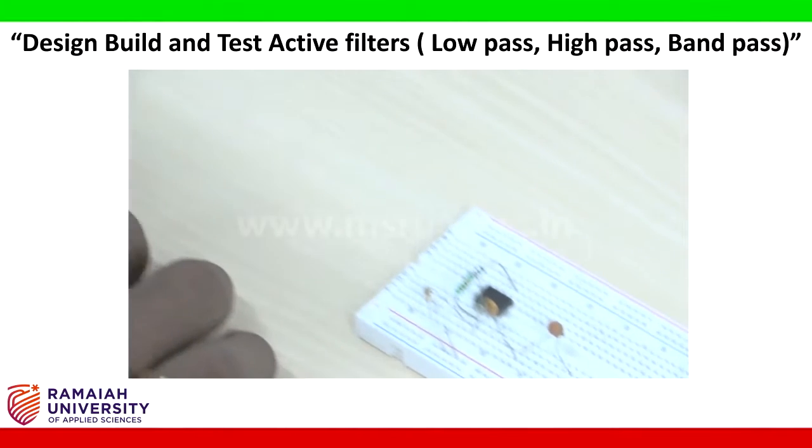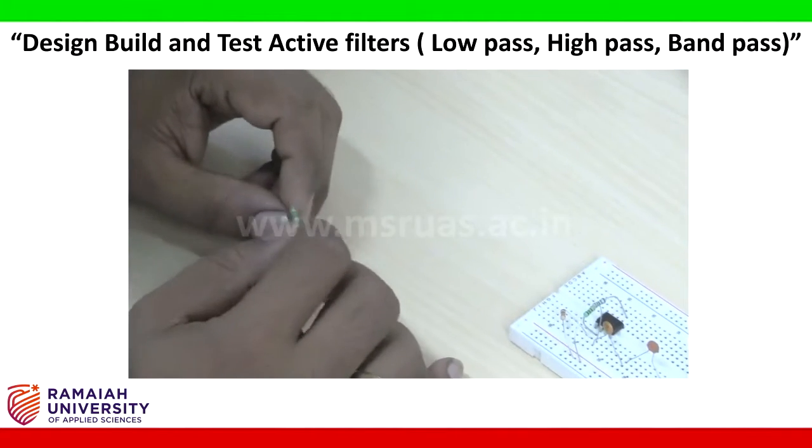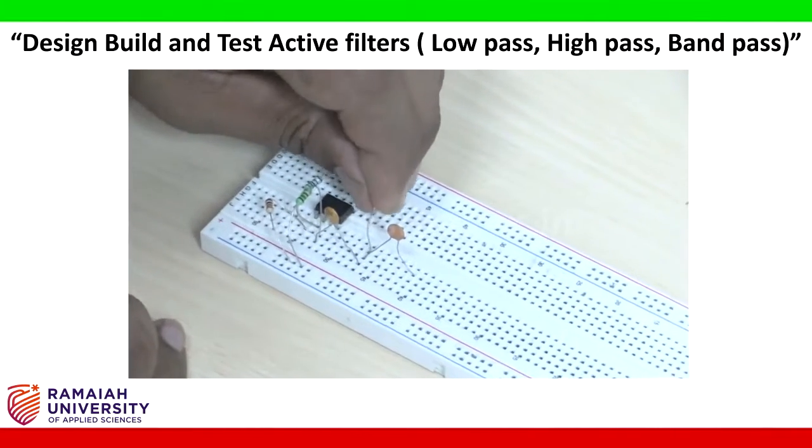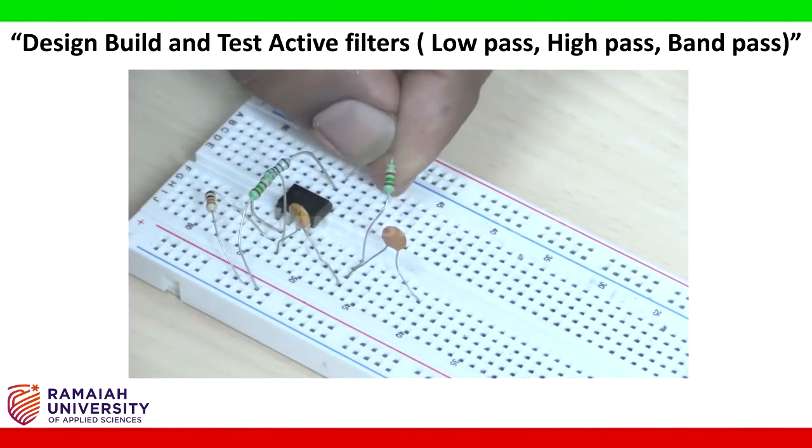After that I am taking a 1.6 kilo ohm resistor, and this 1.6 kilo ohm resistor will be connected to the junction of these two capacitors and pin number 6 like this.